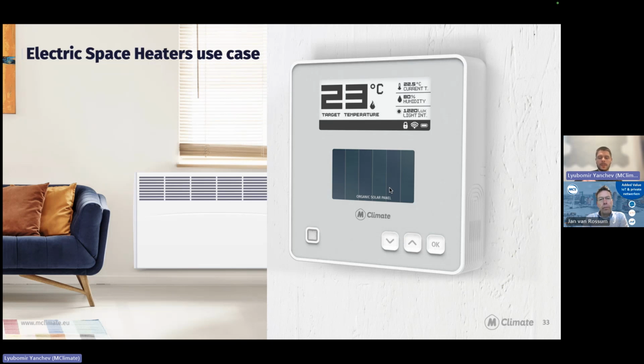In this case, the 16 ASPM, since it also measures the usage, can be paired with a wireless thermostat, so that on the wall we have a beautiful looking battery-free thermostat that can also monitor for occupancy. You can adjust the target temperature from there, and it also measures the temperature and instructs the relay whether it should turn the heater on or off.